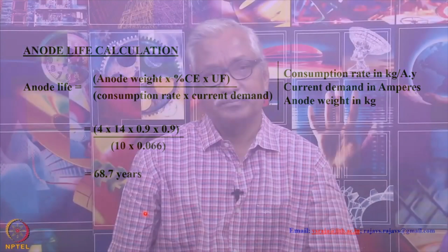So, in today's lecture we looked at 3 important concepts, and we used calculations to clarify these concepts. The first was that the taper slope is very important. Even when we describe the cathodic protection criteria in terms of, let us say, the 100 millivolt criterion, you see how the taper slopes can change whether a metal will be adequately protected or less adequately protected.